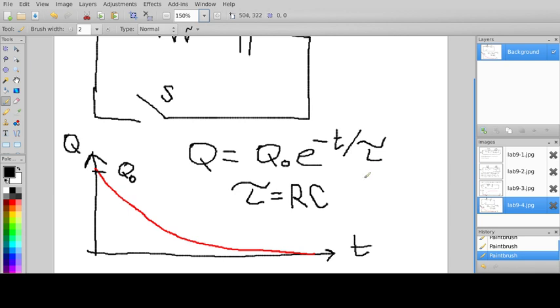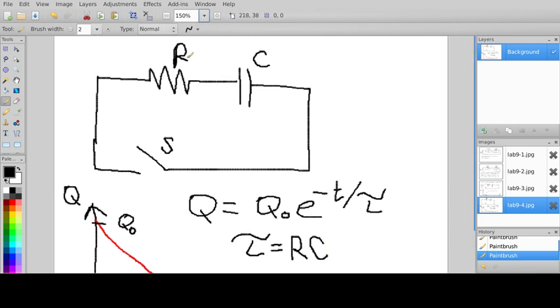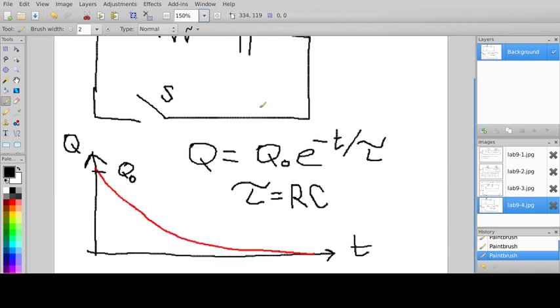And once you've got that, is that equal to RC? Because after all, you put R in the circuit and you put C in the circuit. So theoretically, you could just multiply R and C and you would get tau. Experimentally, you can measure tau by looking at two different times off of the oscilloscope capture, and you would say, okay, are the two taus equal to one another? Yes or no? And if they are, well, then the theory is verified. If they're not, well, then something went wrong, either in the theory or in the experiment.